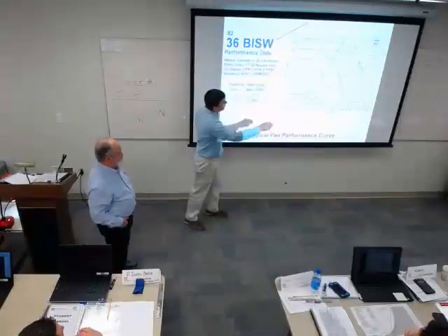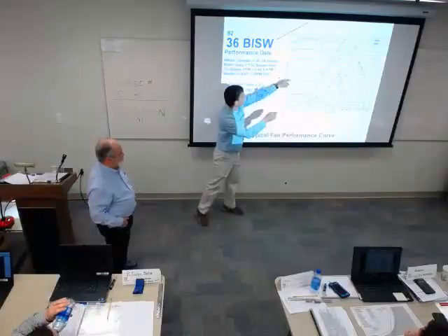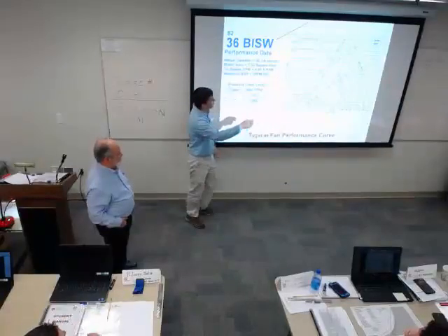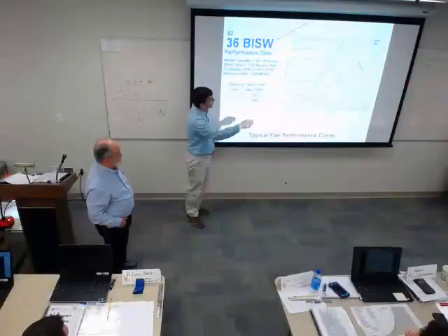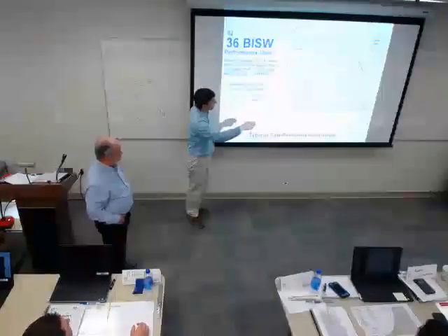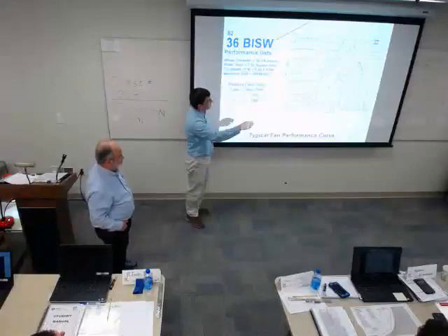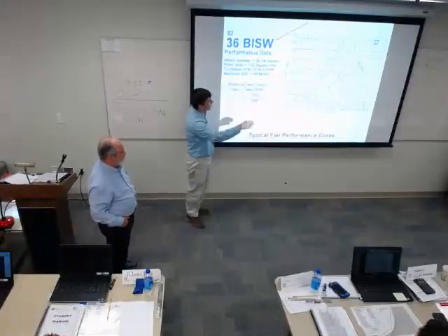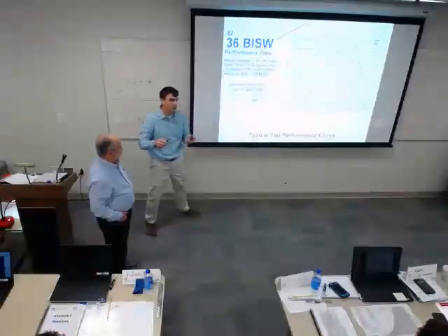Anywhere over here, I'm on a flat portion of the curve. If I'm operating at 5.5 inches of static pressure, that can correlate to any flow rate realistically from 0 to 6,000. So I'm also unstable because this fan is wanting to move on its flat portion of the curve. There are two separate issues there.